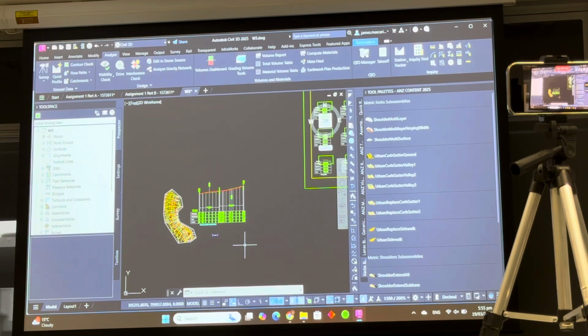If you've got something in 3D, and you click there, click there, click there, and say I'll do a hatch, the hatch command doesn't work in 3D. It wants you to click on something in 2D. So that means the Z values need to be altered.